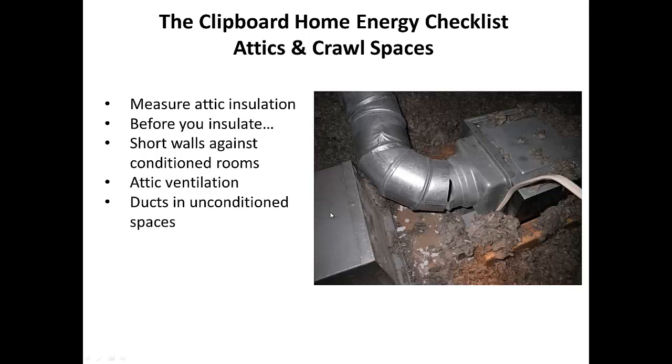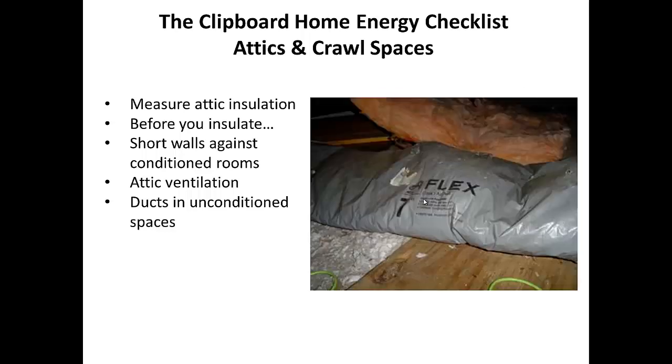Another thing to look for are ducts in unconditioned spaces, and whether it's a return duct or a supply duct, this is a place where hot air in the summertime or cold air in the wintertime gets right into your ventilation system, your HVAC system, and causes real energy problems.